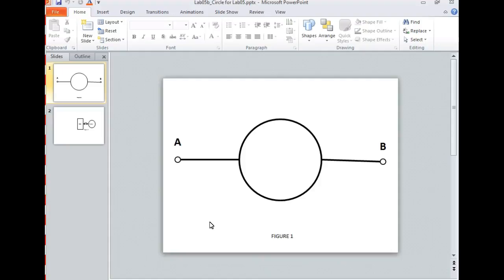We're going to approach point A. We'll come in with a couple of joint moves. Two staging is usually what we want you to do. And then we'll move down to point A. I forgot the height, but it's pretty close. And then we'll do what? Then we'll move over to the circumference. Then we'll come around. And then we'll continue on.